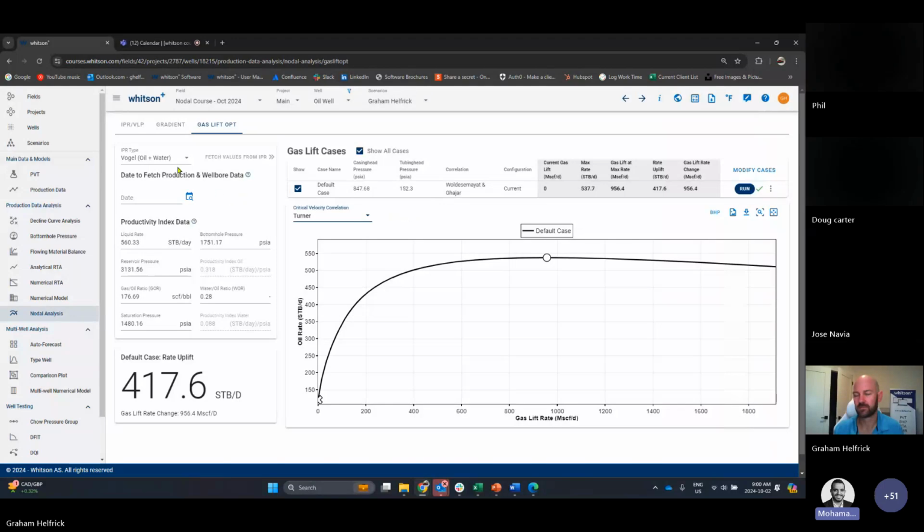But the main thing with this is, I'm giving you a gas lift rate that I think is optimal for you. Maybe this plot shows you that you should inject less. You don't need to inject that much, but the oil rate is not the whole part of the story. You might be injecting just because you want to go above the critical rate to lift. So this would show you that. It would show you that if you reduce your gas lift rate, maybe you'll have the same amount of oil, but you'll end up maybe loading the well. So if that was the case, it would show you that more specifically. Many people would argue it's more applicable for gas wells, but we still have it for both gas and oil wells if you would like to use it, because it was requested.